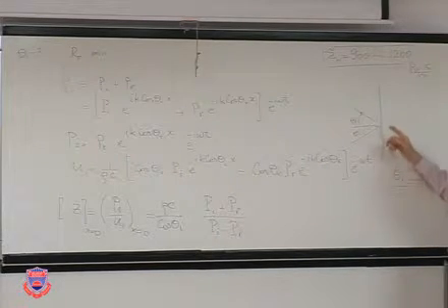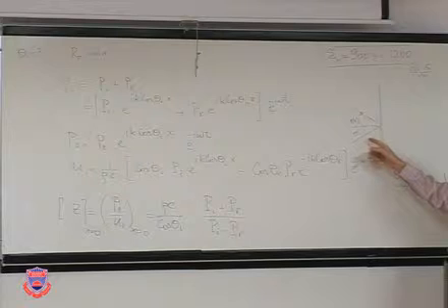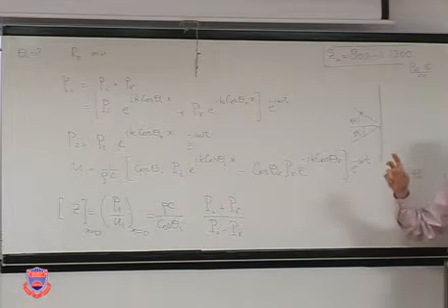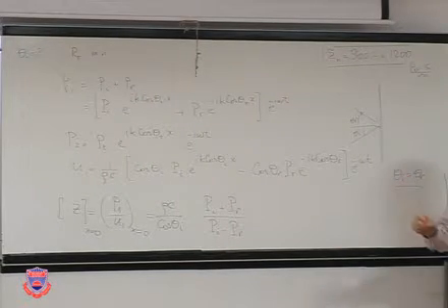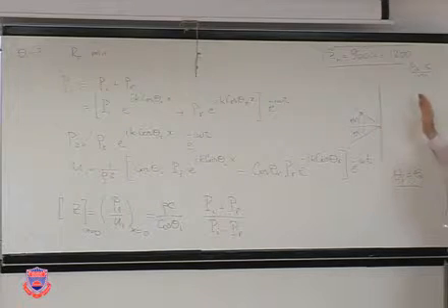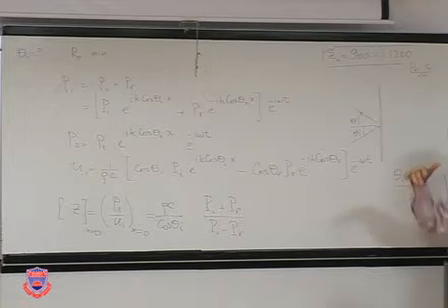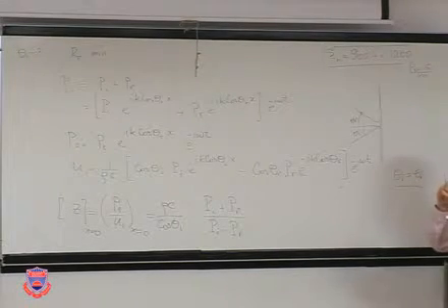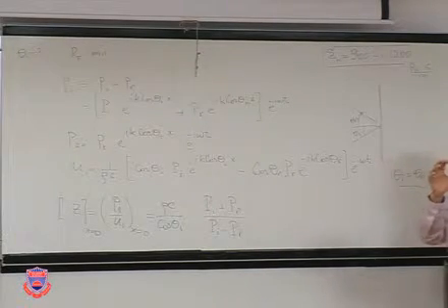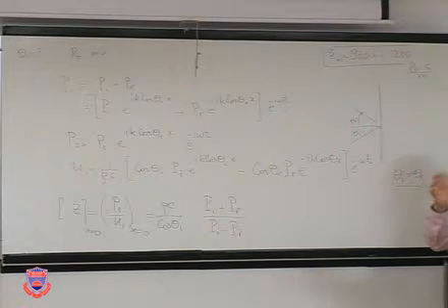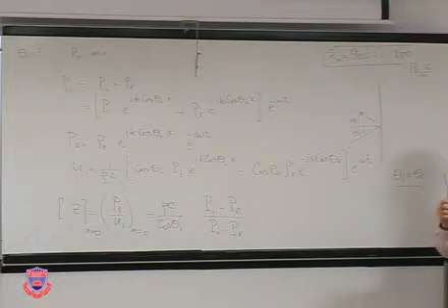Okay? And acoustic impedance, usually the types of boundary conditions we have used in the past, if you remember, we said either rigid surface, open, pressure is 0, or particle velocity is 0. But I also told you once that what happens if it is neither, something in between, then you use impedance.